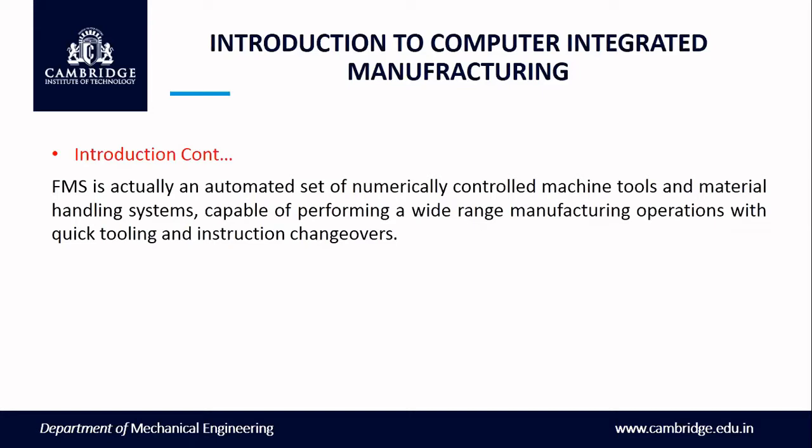That is, the material handling will be automated, capable of performing a wide range of manufacturing operations with quick tooling and instruction changeover. As for example, in a day, I'm just doing spark plug. After 1 hour or 2 hours, I have to change for another thing. Such kind of a facility I have to develop in our manufacturing industry. That is the main reason why we have to shift to the flexible manufacturing system.